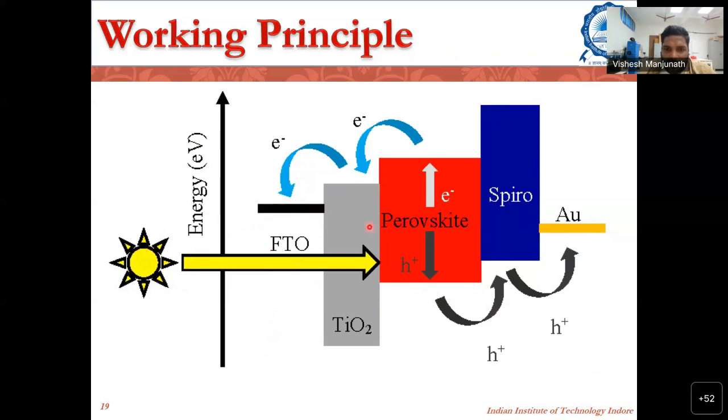So here, if you use again a metal contact, you cannot actually shine the light on the cells. So people here go for transparent conducting oxides, either FTO, fluorine doped tin oxide, or ITO, indium doped tin oxide. And the TiO2 is a semiconductor which absorbs UV light and allows the visible to pass through it.